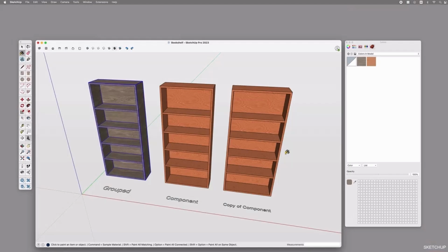So in the previous video, we have used some wooden texture from the SketchUp built-in materials. I also mentioned that once you apply a material, it will be saved under the Colors in Model section. Now, if you have many colors in one file and have a hard time finding one as the colors and textures are appearing within this window, you can always use your eyedropper function when using your bucket tool. This way you can select the material you want to edit and it will appear selected within this window. Remember, it's not the same pipette as in the color window.